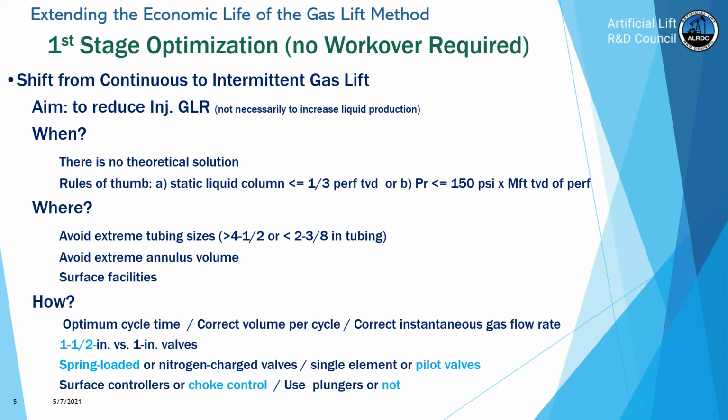So basically, all the gas that we pass into the tubing per cycle comes from the annulus, and that has a very good effect on the high pressure side of the system. We can have many wells on intermittent at the same time, but because most of the gas comes from the annulus, the injection pressure of the gas lift manifold will not decrease.